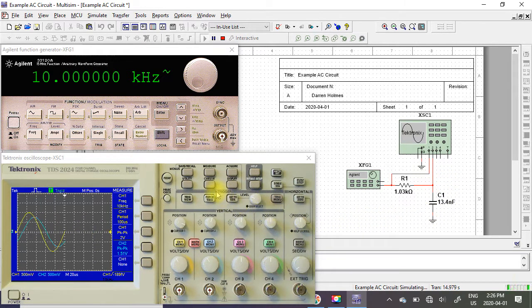So to do that on our oscilloscope, we have something called a math menu. Now, when using the math functions, it's important to have both channel 1 and channel 2 on the same volts per division. It's also important the waveforms are shown on the oscilloscope screen, because if the waveforms go off the oscilloscope screen, the measurements are no longer going to be valid.